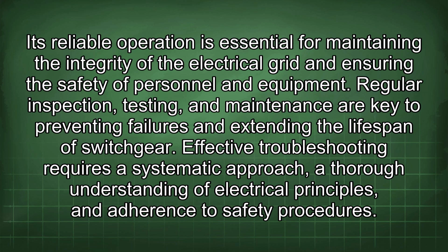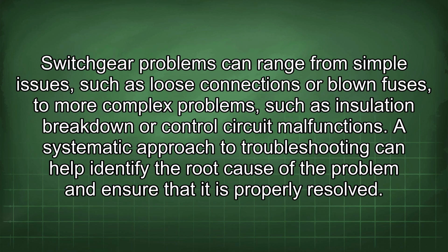Regular inspection, testing, and maintenance are key to preventing failures and extending the lifespan of switchgear. Effective troubleshooting requires a systematic approach, a thorough understanding of electrical principles, and adherence to safety procedures. Switchgear problems can range from simple issues, such as loose connections or blown fuses, to more complex problems, such as insulation breakdown or control circuit malfunctions.